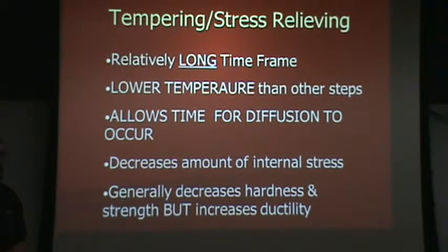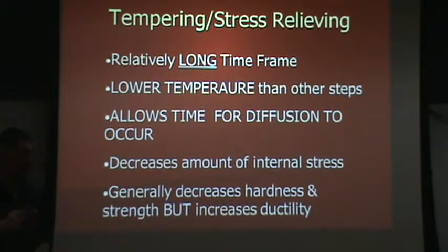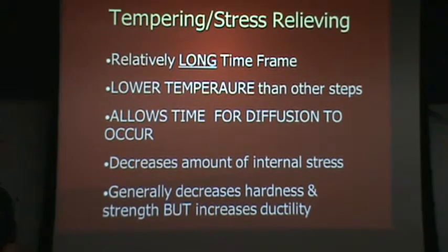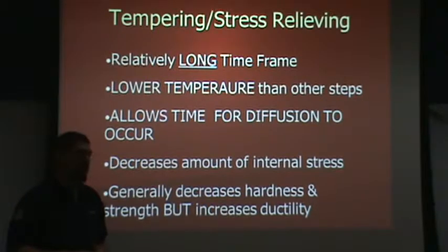What's the reason for the tempered martensite brittleness then? I knew you were going to ask me that. I don't have the answer off the top of my head, but you can find it in George Krauss's book. I actually have it marked in my book, I should have brought it with me. I have a sticky note there because I've looked it up on numerous occasions. I think that's one of those phenomena where they have ideas about it, but they're not 100% sure yet exactly why. These are things that often are related to what's happening at a very, very small scale along grain boundaries. They talk about things like partitioning, phosphorus, and things like that. So these are the kinds of things that you would study with the TEM.